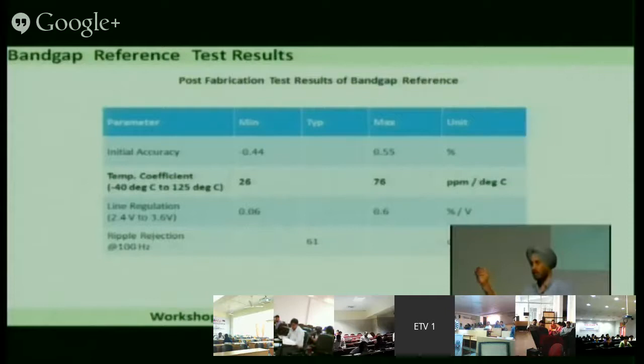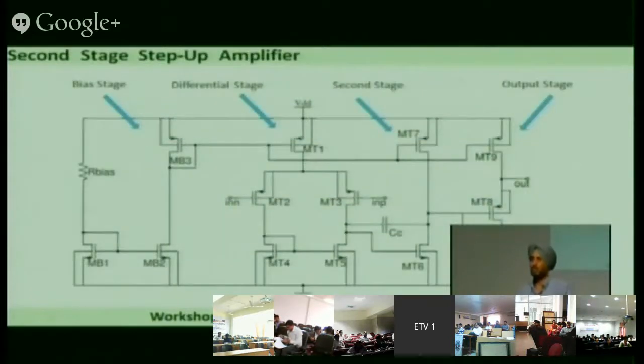If in the input signal the ripple is, say, 1 millivolt, then at the output it will be 1 millivolt divided by 1000, which becomes 1 microvolt. So a 1 microvolt ripple will be there. So we have divided this by 1000, and the bandwidth is 100 hertz. So this is how 1000 times is 60 dB, 20 log 1000. Log 1000 is 3, multiplied by 20, so it becomes about 60 dB. So these are the results which are actually measured. Now come to the second stage.